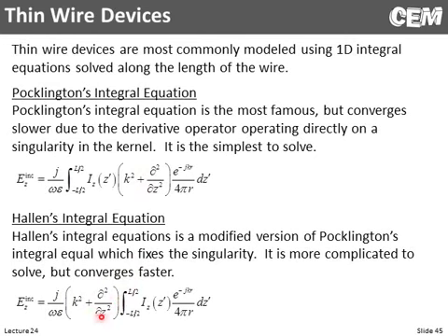And it turns out this numerically is a little bit better, although this is more difficult to implement, because we're dividing by r here. And this r term can go to 0, which of course makes this go to infinity, and that's called a singularity. And so we sort of have this sharp spike here. And to make things a little bit worse, we're taking a second order derivative of that sharp spike. That's bad.